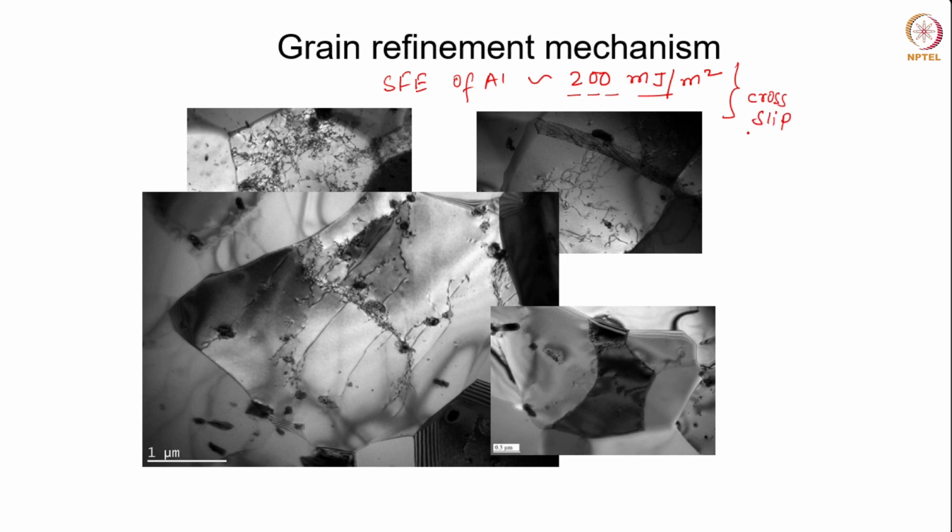Okay, and therefore the dislocations will be able to move during this deformation process and they will arrange themselves into such boundaries, leading to formation of these small grains inside a big grain, which will ultimately break this grain into more than one grain and lead to grain refinement. Okay, but there is little more to understand over here.